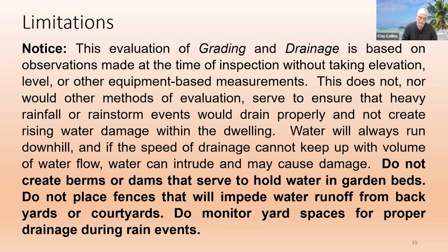On fences, you might have a very nice swale, and then somebody comes in and they build a fence, and there's so much water running off, they have a gap between the bottom of the fence and the soil, and their dogs get out, so they start damming it up. And the water comes in, it can't get past that fence, and it's going to hold it longer than it should, affecting the foundation. And you can see cracks in that area caused by the water dam.